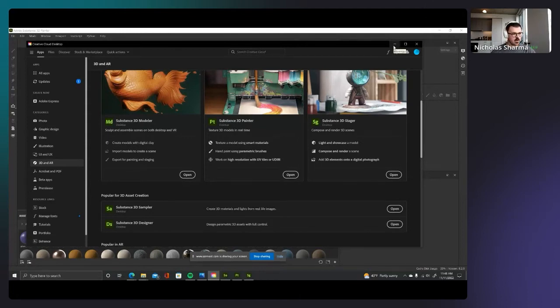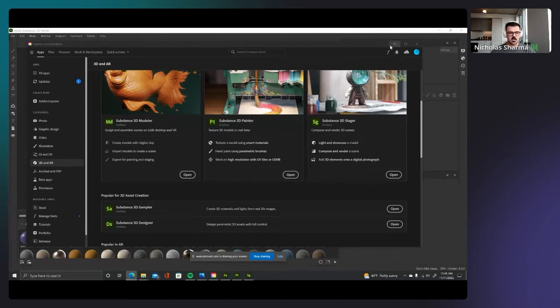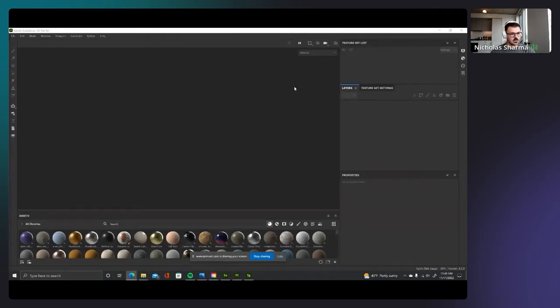If you're working out of Gravity Sketch, one of the best practices I recommend is, when you're finished with your project, save your project out as an FBX, have your normal set to welded, and choose mesh, which is the better format instead of NURBS, when you're exporting out of Gravity Sketch.